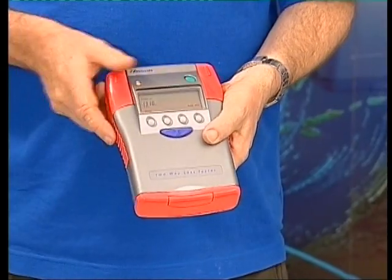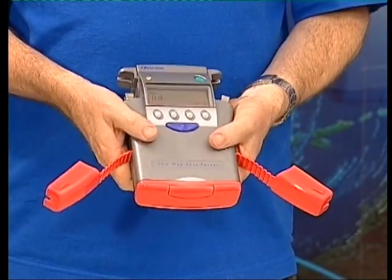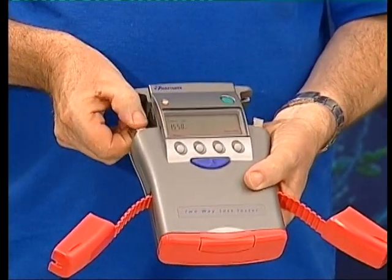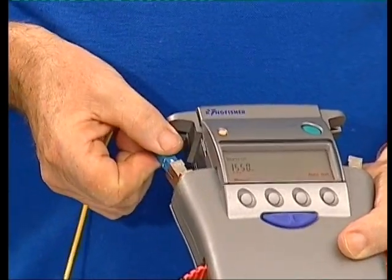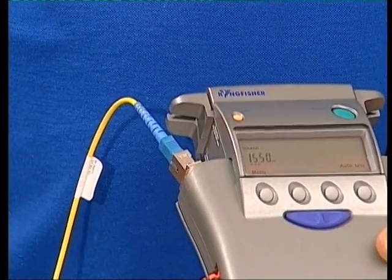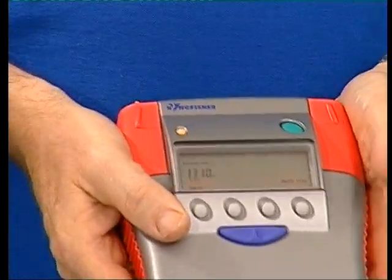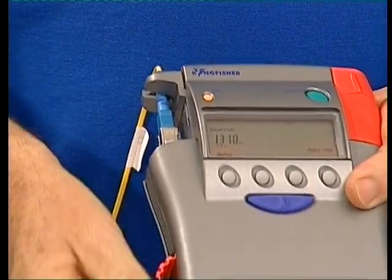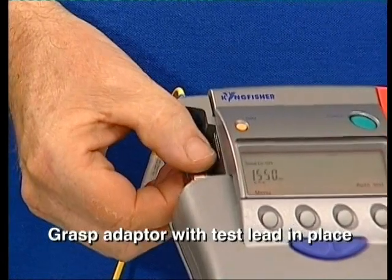Our patented optical connector offers numerous practical benefits. The same arrangement is used on both test ports of the instrument. When adding a patch lead, rotate the connector to the open position for easy access. Insert the test lead and then close both the connector and the protective boot. Connector adapters are easily removed using one of two methods. Either way, it is usually easier to grasp the adapter with the test lead in place.